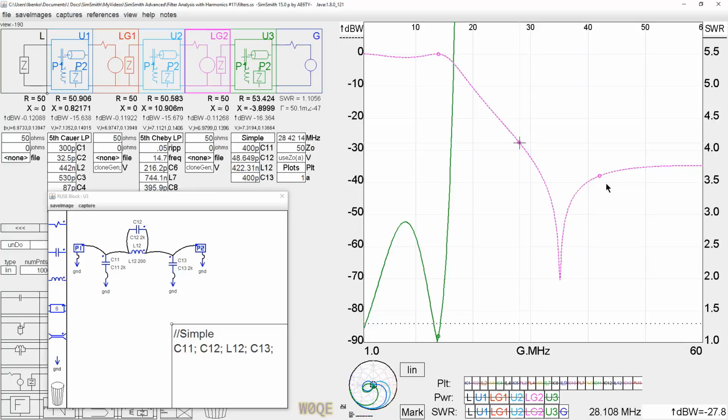It does work. Our third harmonic is 38 dB down, right down here at the bottom, and typically the third order harmonic on an LDMOS amplifier is pretty bad. It can be as bad as maybe 13 or 14 dB below the carrier. So 13 dB on top of this gets us 51. And 51 is good enough below the 43 to be good. So we could say that this circuit is actually an acceptable filter.